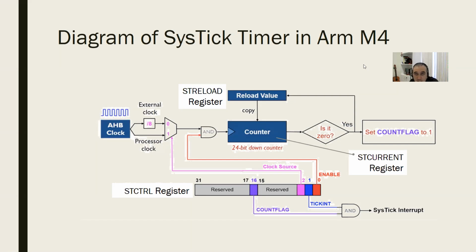In that sense, let me remind you, we had 3 control registers to control the timer in this device. 3 control registers. The first of which was the status control register. As all registers of the system, it is 32 bits. However, most of the bits being reserved. In other words, not used or don't care. All the same nomenclature. And we were using only 4 bits. Bit 0, bit 1, bit 2, and bit 16.